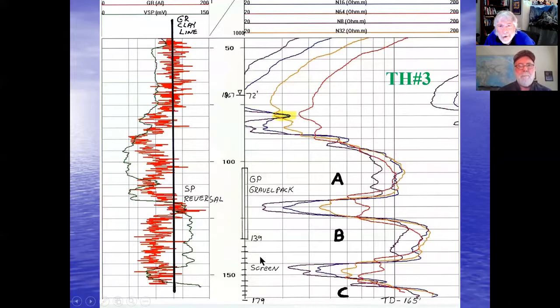And again, part of the problem was the client's municipality well at this site. We basically had a screen that came across the lower horizon, which was all right, but we had a gravel pack that came across B into A, and then we had a kind of endless up here. So we came through here and perforated and squeezed out this area to isolate A from B, and we got the client better quality water, except we lost on the quantity of water, but they are appreciative of the better water that they got.